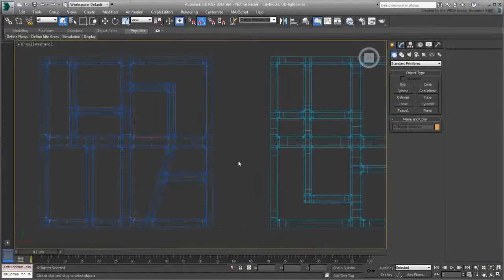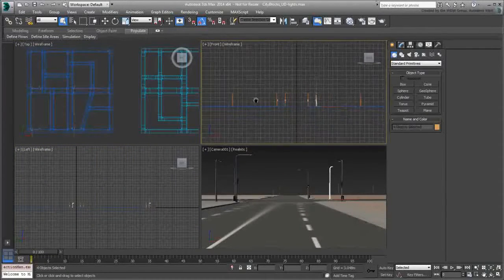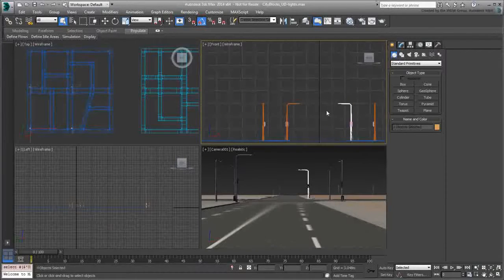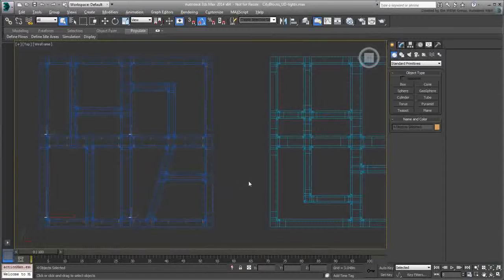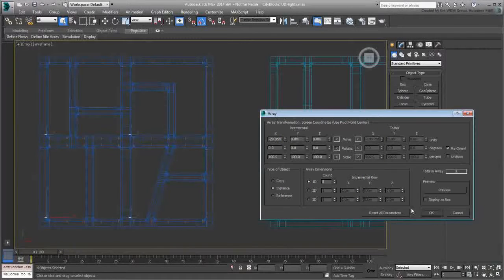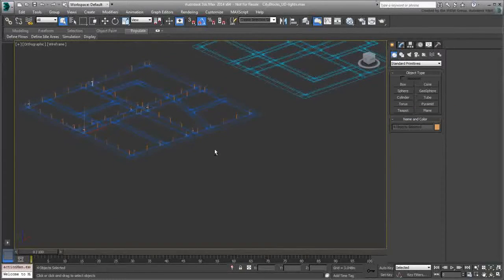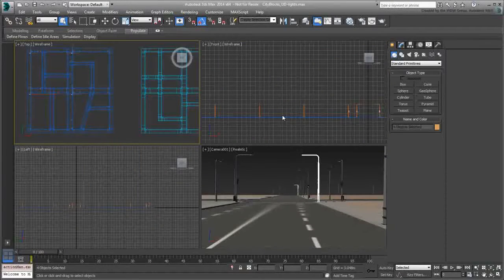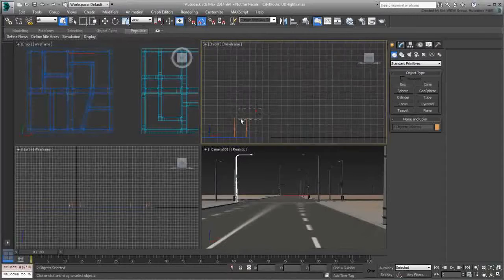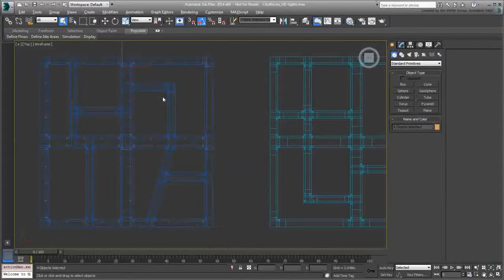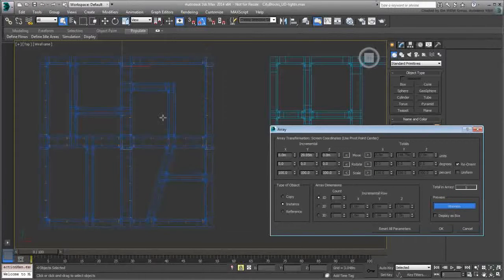Use the same technique to clone the poles running vertically. To that end, use the front view to make your selection, but enter the 29.95 meter value in the Y position field while zeroing out the X value. Use plus or minus values depending if you are cloning up or down.